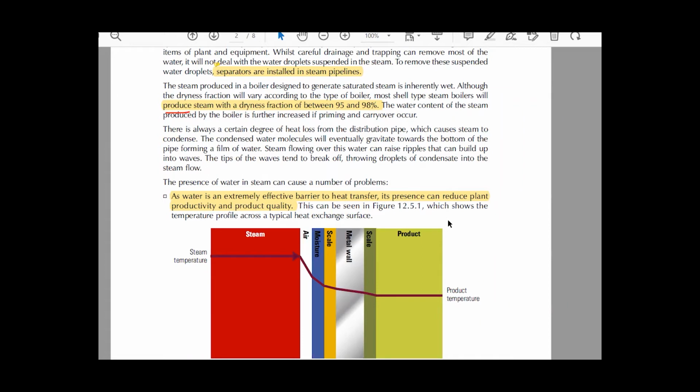According to Bernoulli's equation, the water then has a very high velocity due to this small area. This makes water hammering and damages the valve seats. All these damages I can prevent by fitting a correct separator.